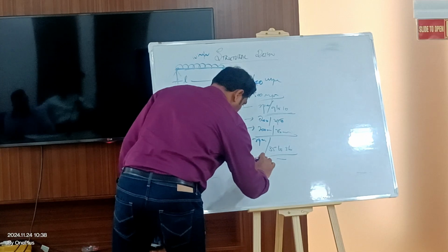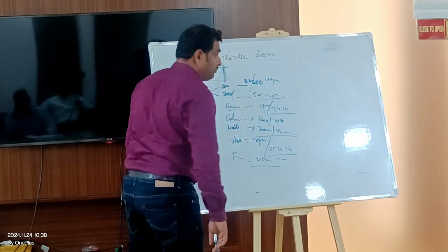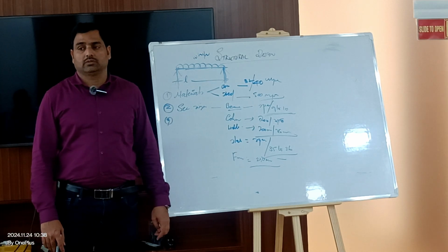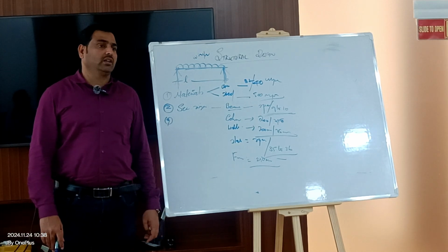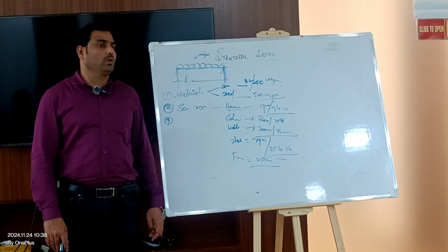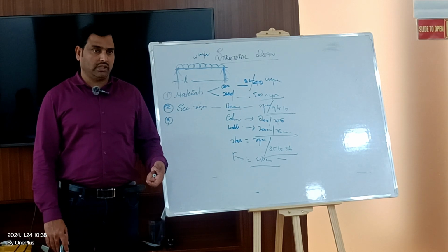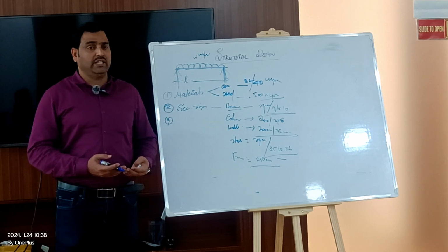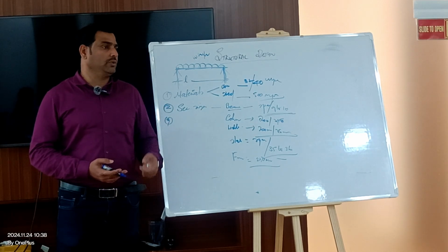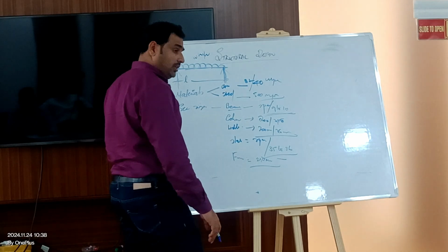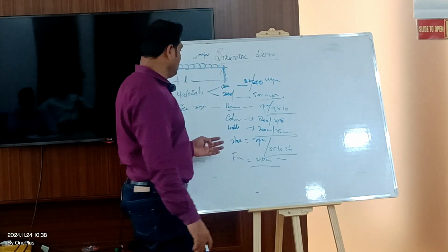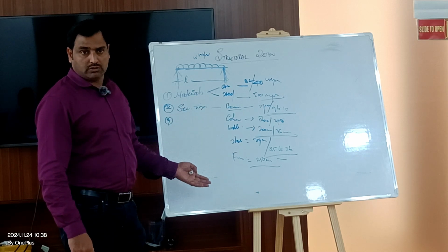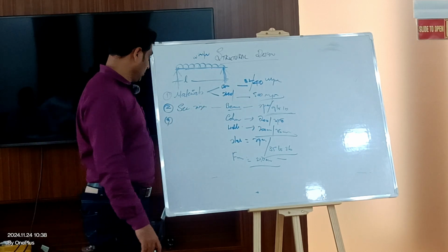Foundation. The minimum thickness according to the code is 250 millimeters. But in practice, we are not using 250. We are using 300 millimeters, right? Because we do have cover constraints. The clear cover is 75, and with the rebar, we need the minimum distance between the bars. It's clear, right? What else? We only have these elements: columns, beams, walls, slabs, and foundation.